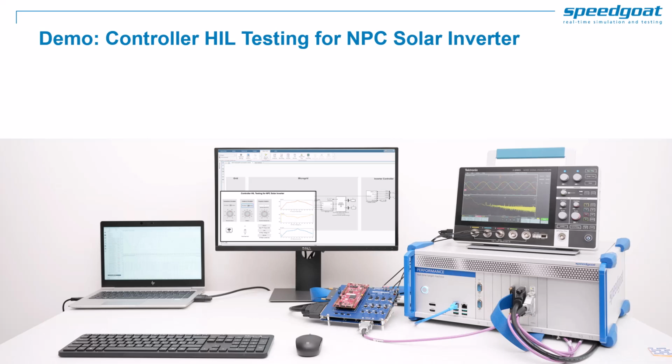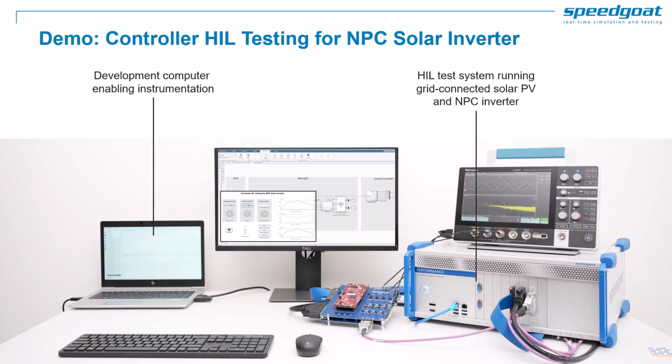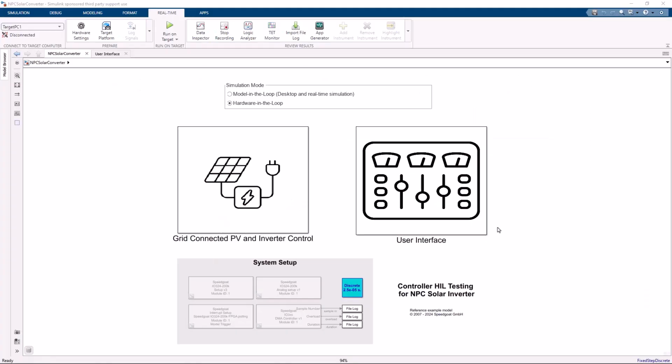Let's now explore a solar inverter HIL setup in action, outlining the CPU workflow with configurable I/O modules. The hardware setup for this demo consists of a development computer enabling instrumentation and real-time testing, a performance real-time target machine running HIL simulation of a grid-connected solar PV system, including an NPC inverter. The device under test is a microcontroller running the inverter controller and MPPT algorithm, as well as an oscilloscope to monitor the voltage and current of the grid and DC bus of the simulated power system. Let's now switch to Simulink and check our HIL system model.